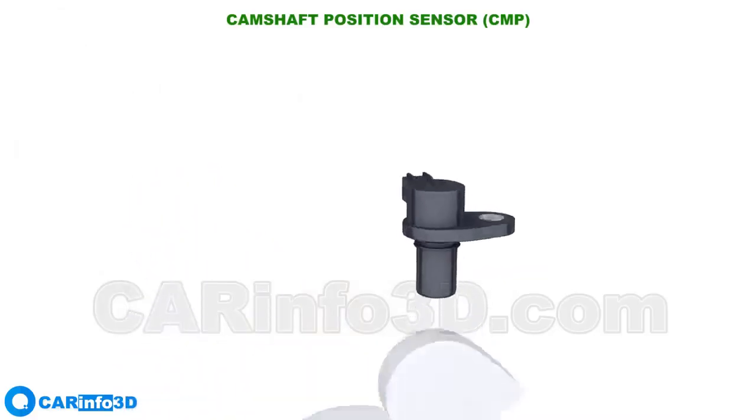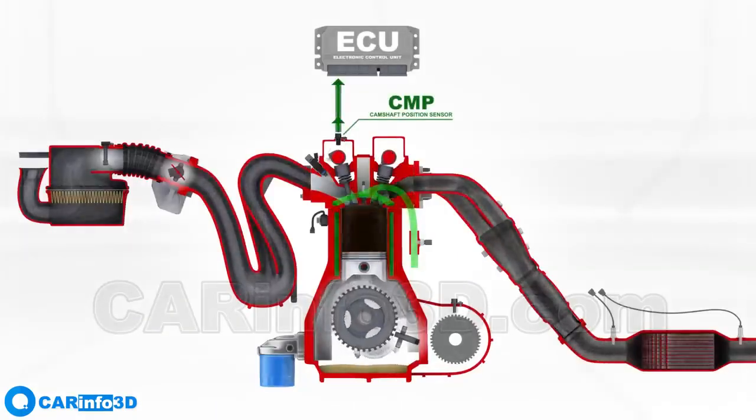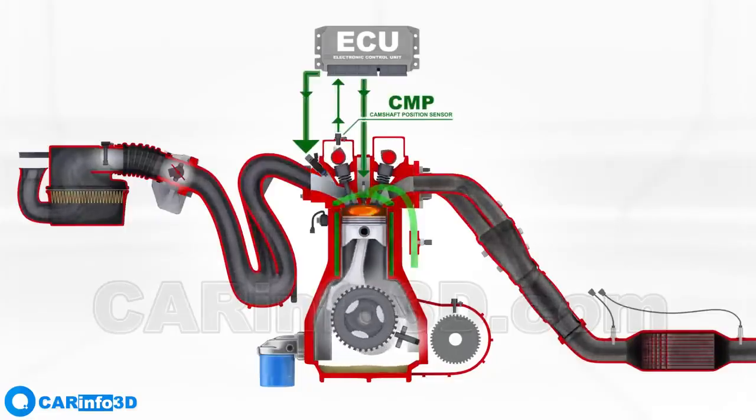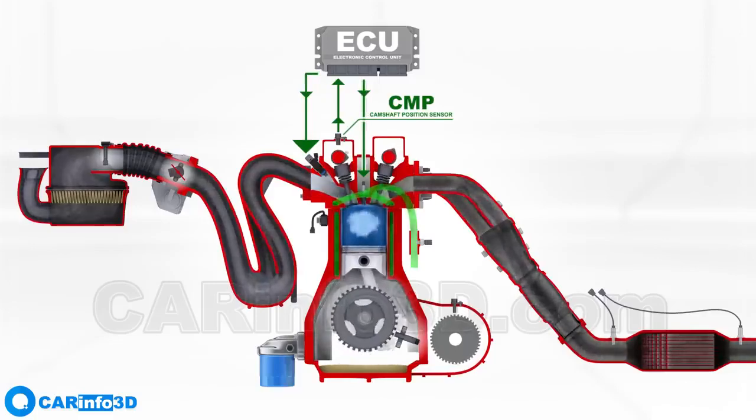The ECU analyzes sensor information to identify which cylinder to inject fuel into and ignite, which is required for multi-point fuel injection, where the injector supplies fuel to each cylinder individually. This sensor is also important for the adequate operation of the variable valve timing system.